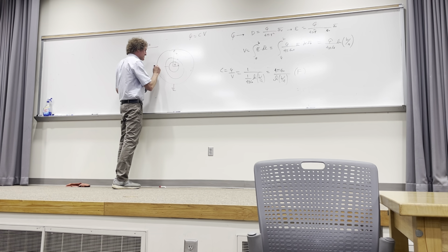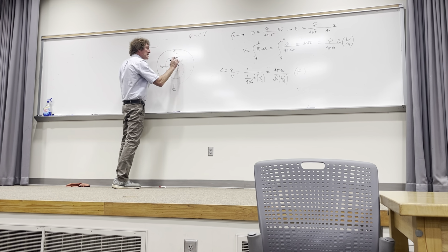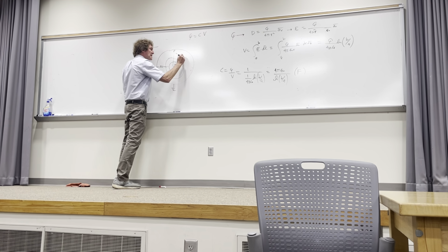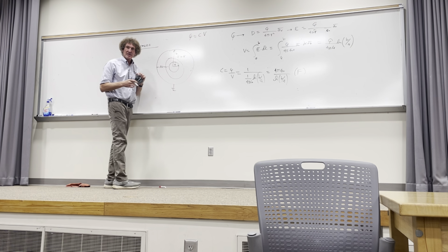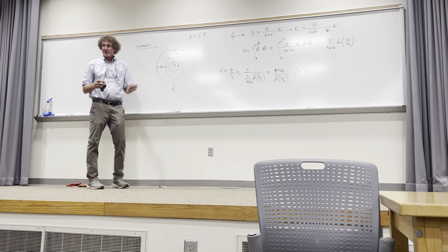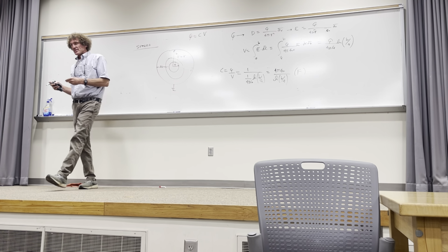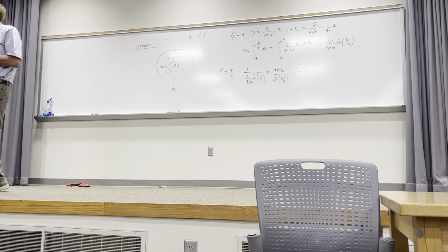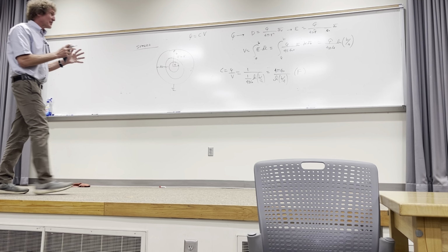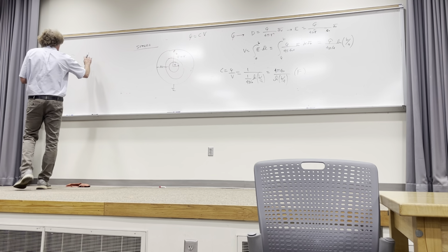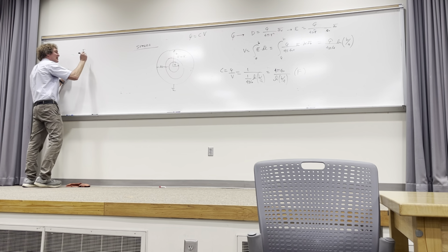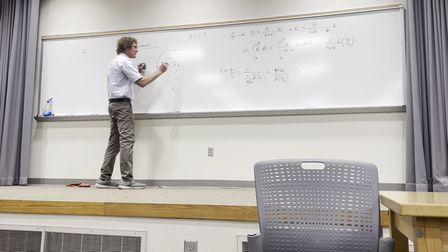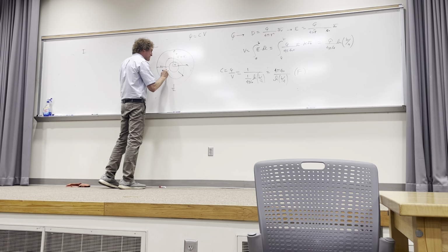I want the resistance between these two. If sigma now is equal to R, just R itself, between the inner and outer conductor. Y'all follow me? For resistance, what did we have to do? Similar, right? But we had to assume something. What did we assume usually? I, right? We're going to assume the total I flowing from the inner conductor to the outer conductor.